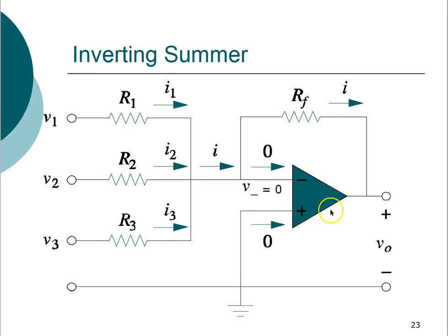And now let's see next. Here is another type of operational amplifier, called the inverting summer op amp. We call it inverting summer because the input voltage is supplied to the inverting side, and the output voltage you get is an inverted output voltage in this particular case. Inverting summer means there will be a number of inputs which will be summed and go into the op amp, and that's what is happening here. V1 represents your input voltage, V2 is also an input voltage, and then you have V3. These are the three input voltages which are connected to the input resistances.